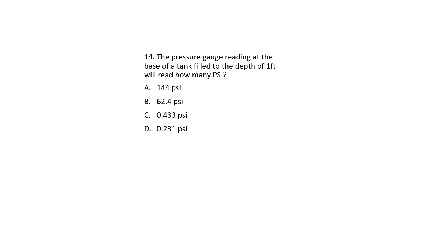The pressure gauge reading at the base of a tank filled to the depth of 1 foot read how many psi? 144 psi, 62.4 psi, 0.433 psi, or 0.231 psi. Pressure, head in feet times 0.433 psi. C, 0.433 psi.